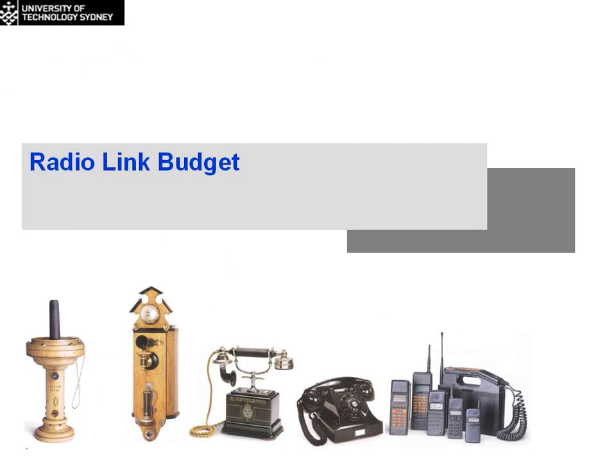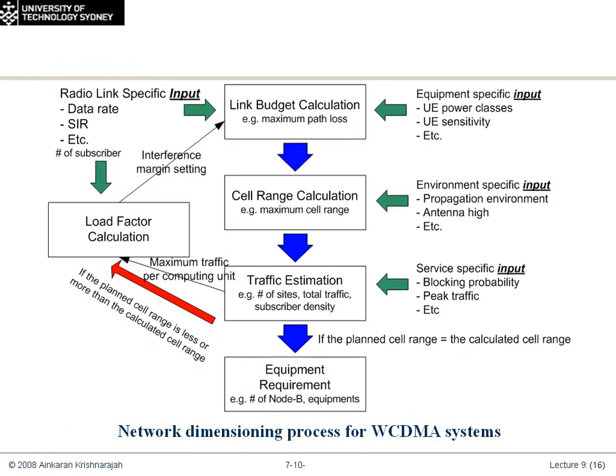Okay, we can move on to the radio link budget piece now. Moving on to slide 16. So in much the same way that we looked at in the previous slides, on slide number 6, which was the RNP process, where we had the inputs and the outputs, now we're specifically looking at the process for the link budget. So the link budget is defined as the radio characteristics, if you like, between the base station and the mobile phone. So that's what we're dimensioning for.